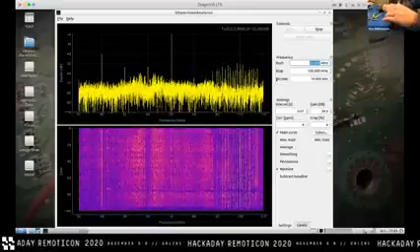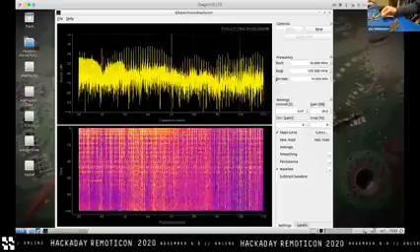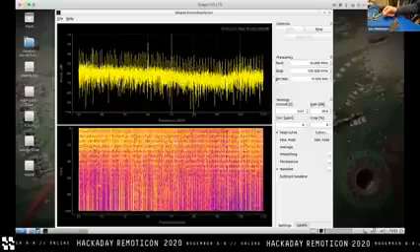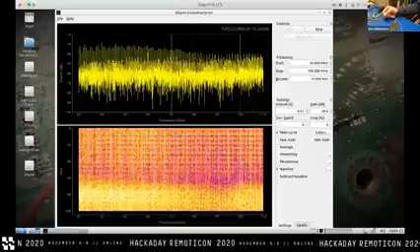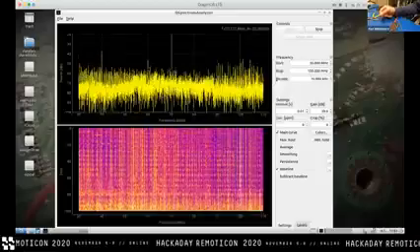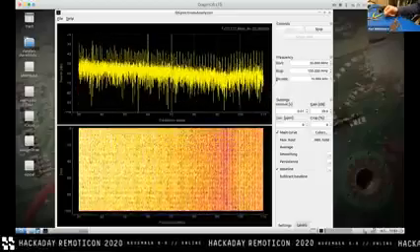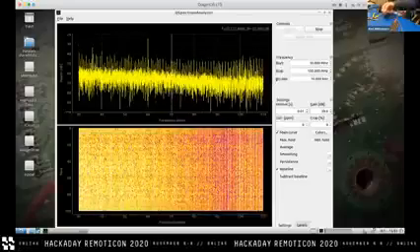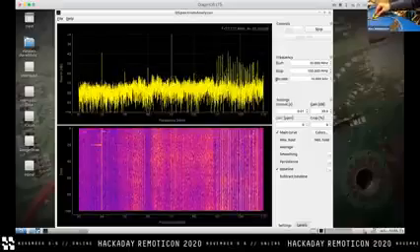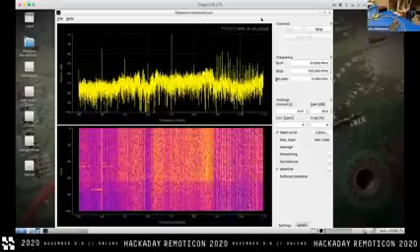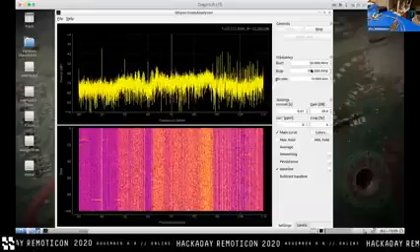Anyway, let's plug in our big wide probe and look around. We've got basically the RSA speed. Granted, it's just on a peak line, but over that massive bandwidth, and we can see all of those peaks. So the HackRF is really, really good for this kind of work because it supports great pseudo swept spectrum analysis features.